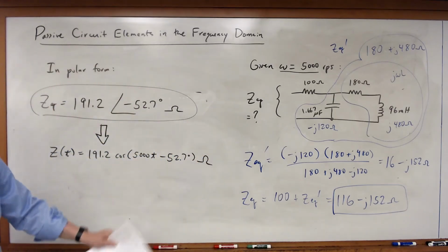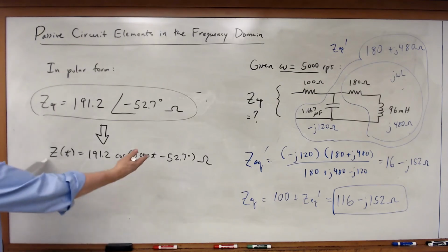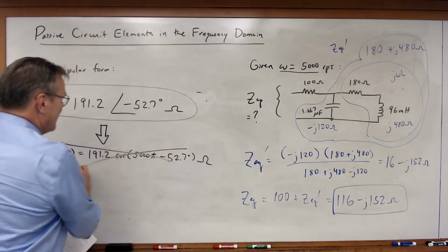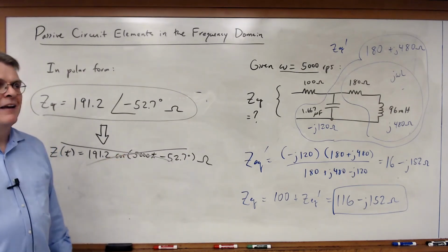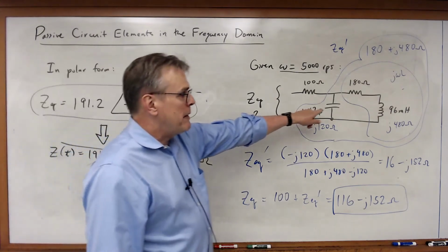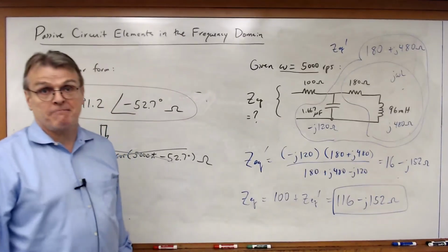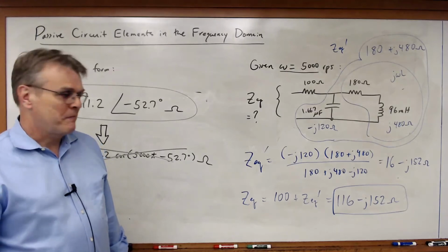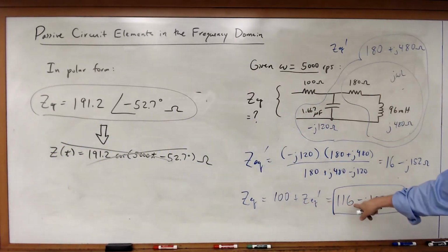I've seen many people over the years make that mistake. They treat it like a phasor. This makes no sense. There's no such thing as a sinusoidal impedance in the time domain. In the time domain, impedances turn back into passive elements. That's what they do.